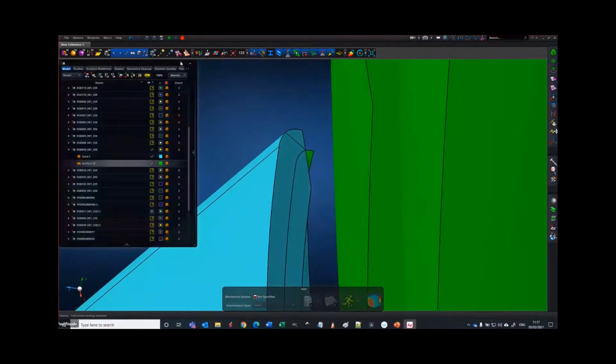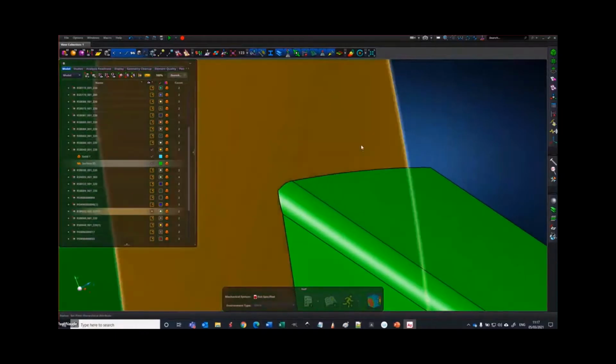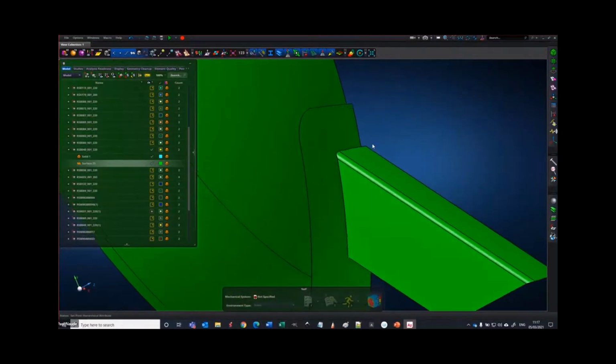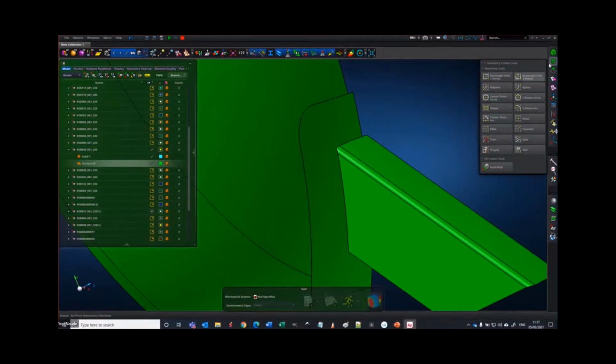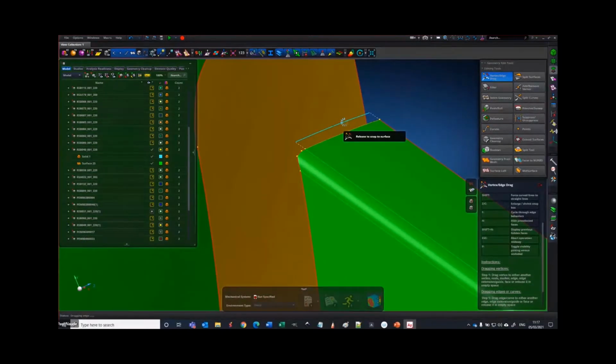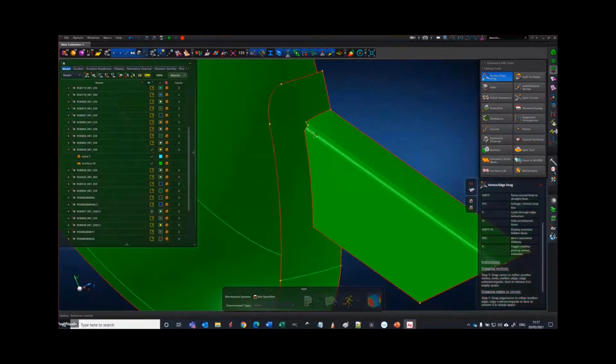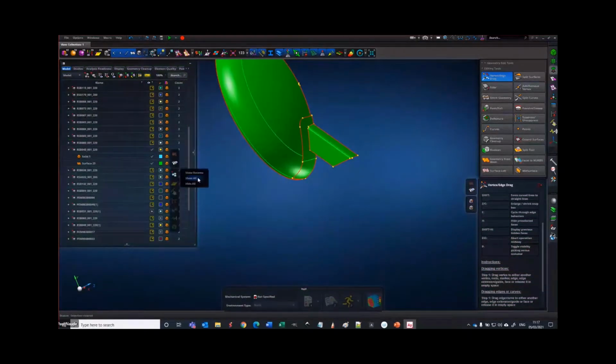All right, so when we already have our mid-surfaces and we don't want to revert back to fix the problem in the solids, we can use our edge drag tool to either drag and extend edges or vertices. Right, so there's a lot of things that we can do to improve the quality of a structure like this.